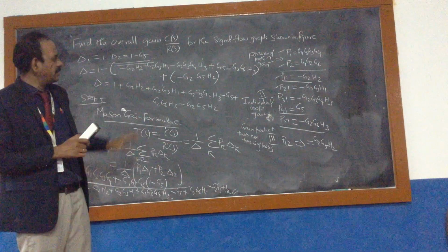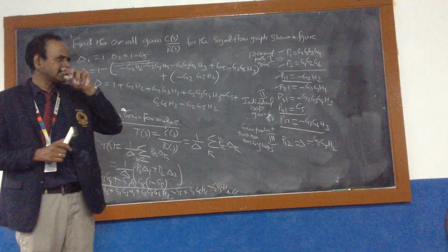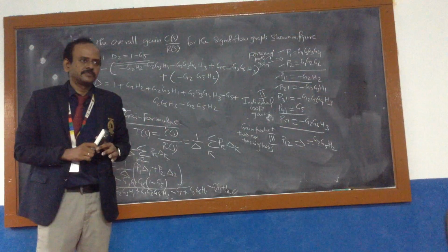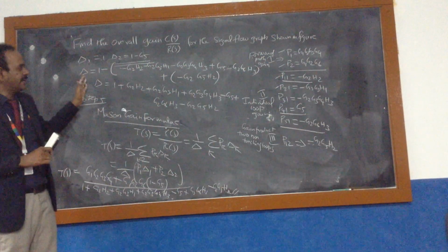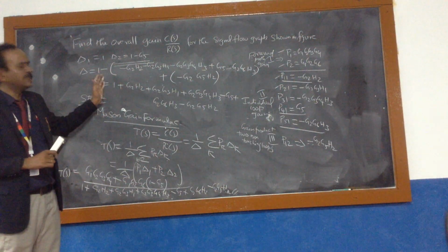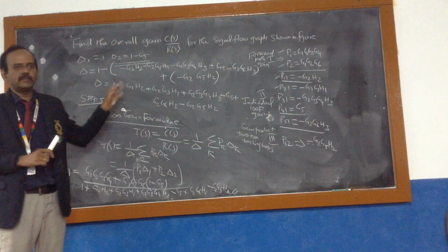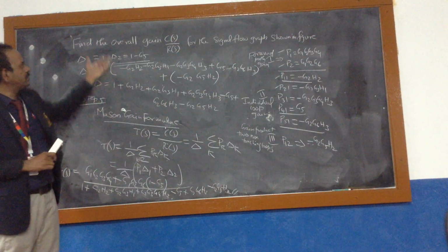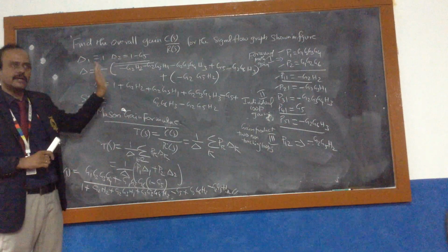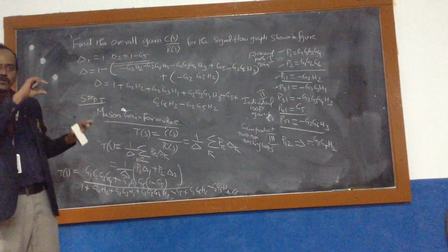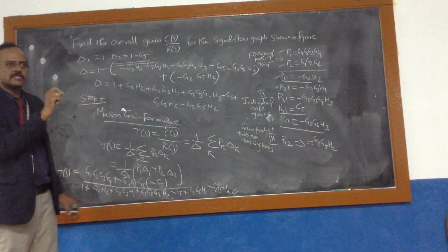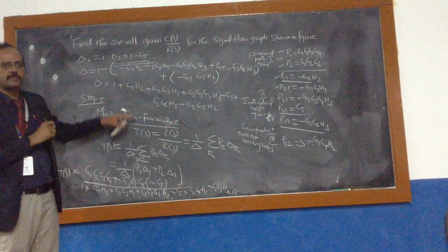In the earlier method, we used block diagram reduction. If the block diagram is given, we have to convert it into a signal flow graph, whatever the question gives. We convert it into the signal flow graph, make the nodes, write the nodes, and then solve the same problem.